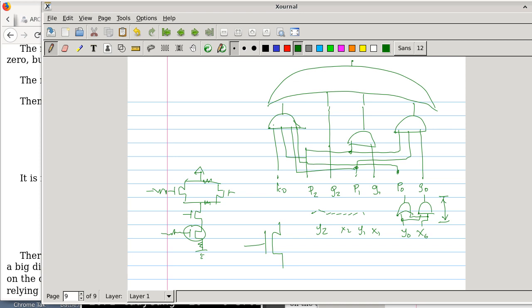Because it has 64 terms, and one of those terms has 64 individual terms within a conjunction. But how many levels of gates are we talking about? 3. So if we assume, regardless of the number of input pins, a gate has the same propagational delay, then all the K's can be computed at the same time, and they will all finish at the same time as well.